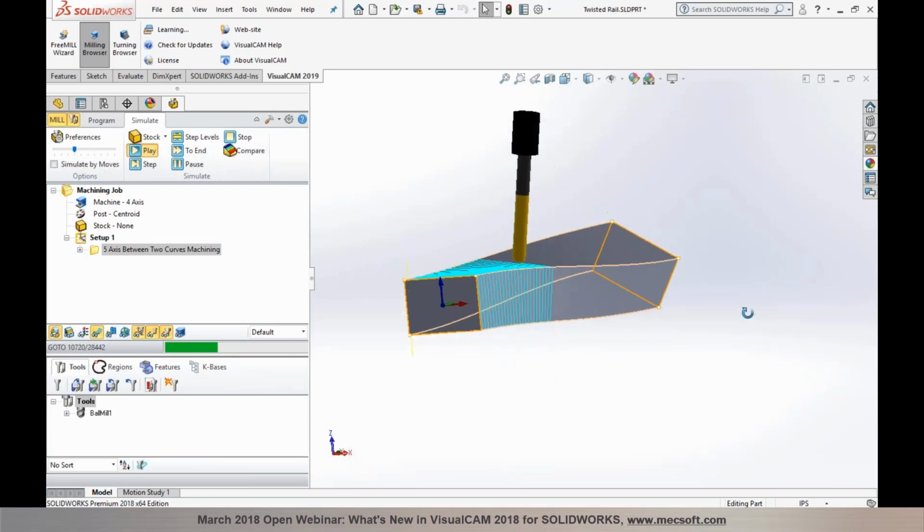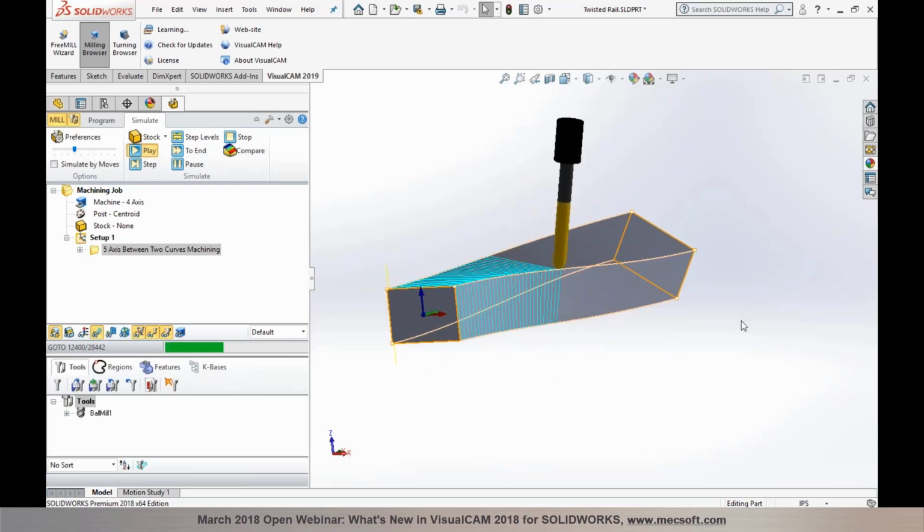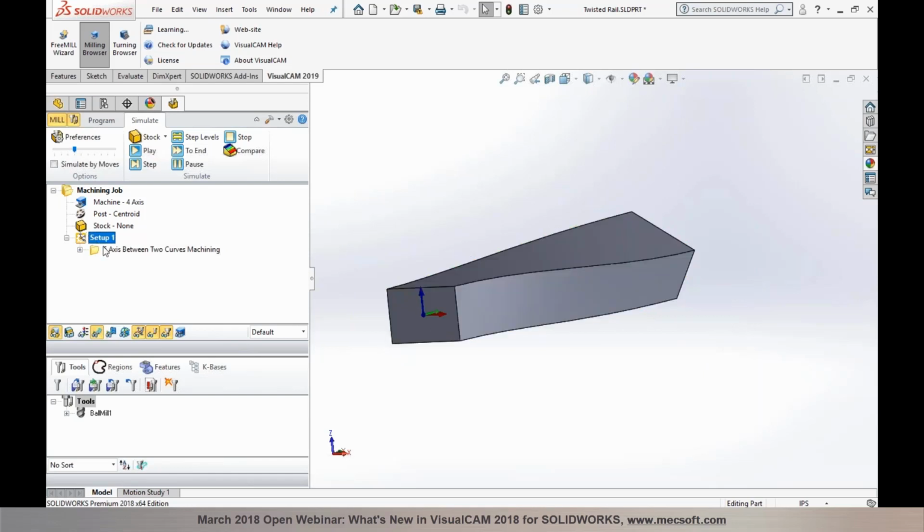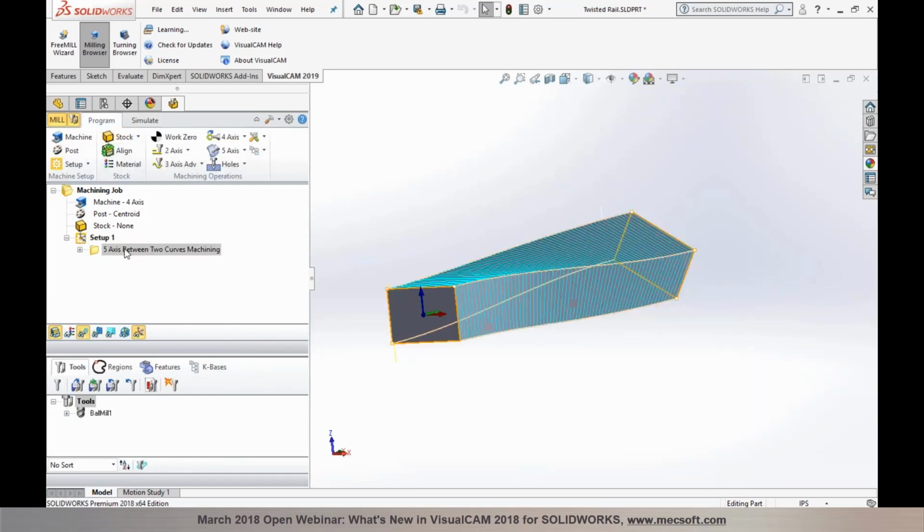Yeah, when Uday says true 4-axis or locking the 4-axis, what he means by that is the tool is constrained to parallel planes that are normal to the rotary axis of the machine. So in a 4-axis machine, obviously you can only change the tool axis in a plane that is normal to your rotary axis of the machine. But in our traditional wrap methods, we keep the tool axis normal to the rotary axis.